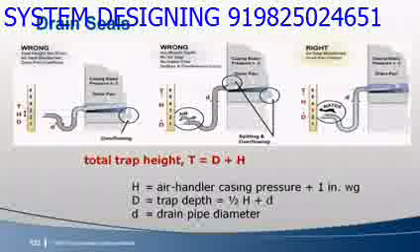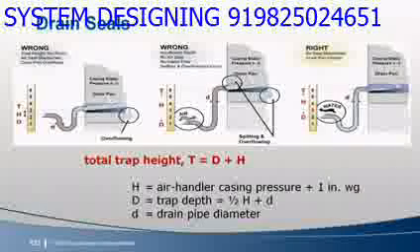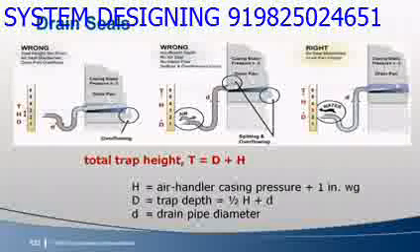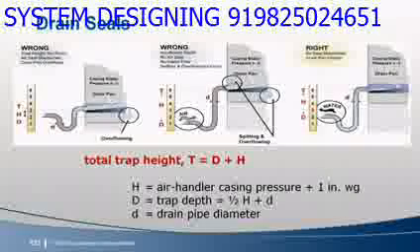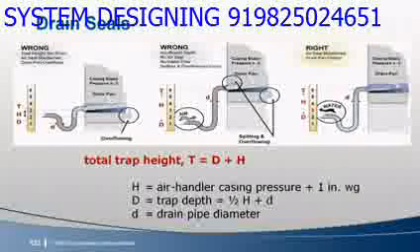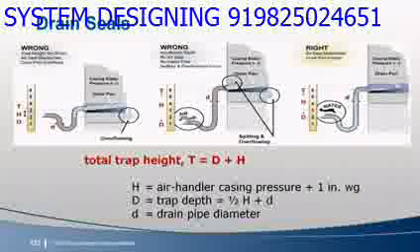The middle design doesn't work either. It's tall enough, but not deep enough. Again, it doesn't seal when the fan is on, so spitting and overflow result. A trap might not actually be designed like this, but if it includes a T-fitting and a plug for cleanout, a loose or missing plug can result in the same kind of poor operation.